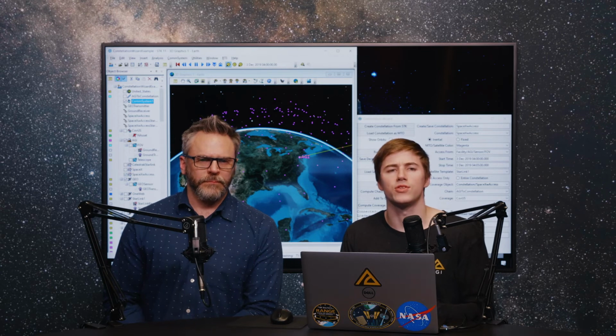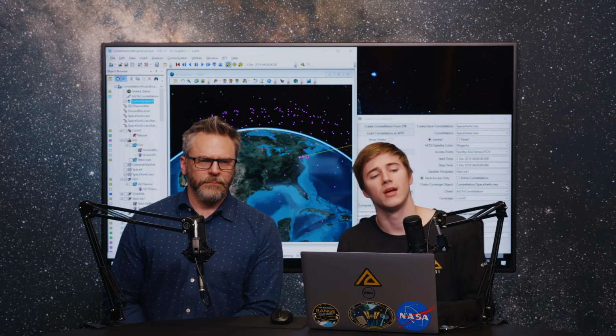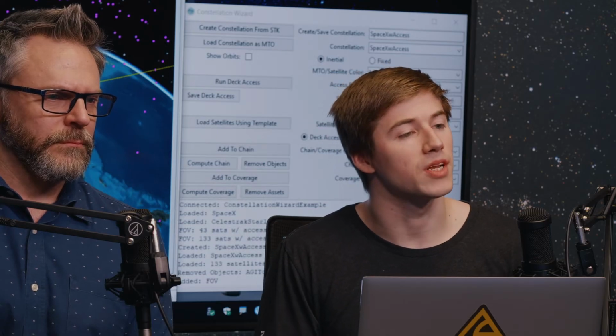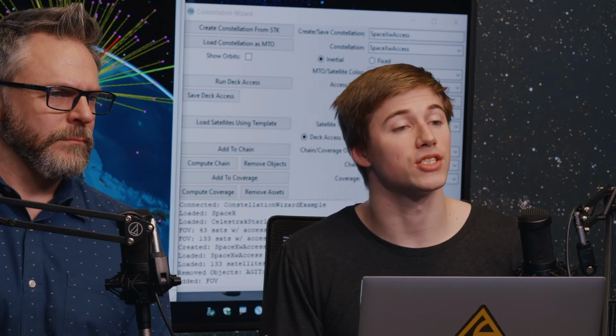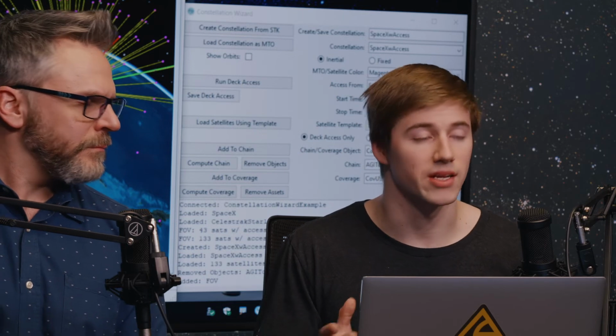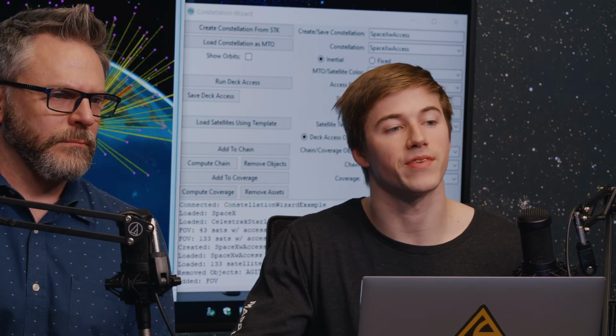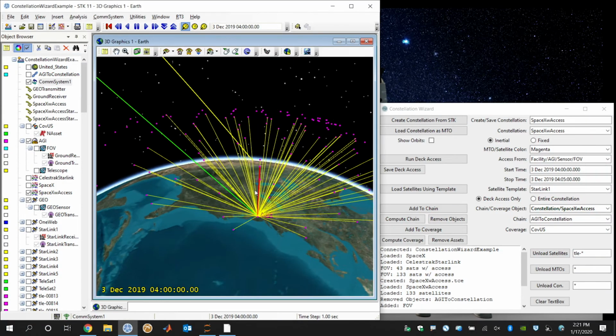Right now, I'm using 13.5 gigahertz for the frequency, which is what I found in the paper I was referencing earlier. And then the communication link to the GEO is at 13.6. And again, this one's just a little bit notional. The frequency really does matter on how much interference you're going to get, but we'll show you that.